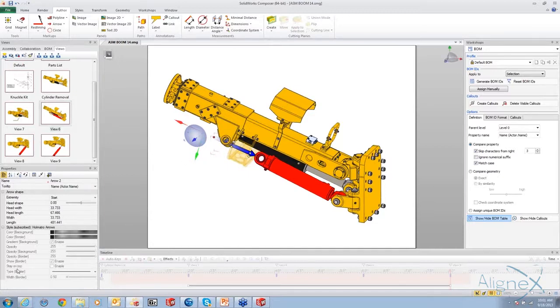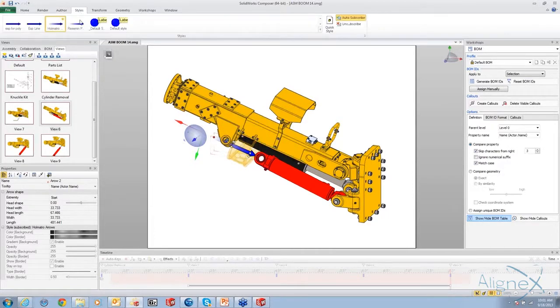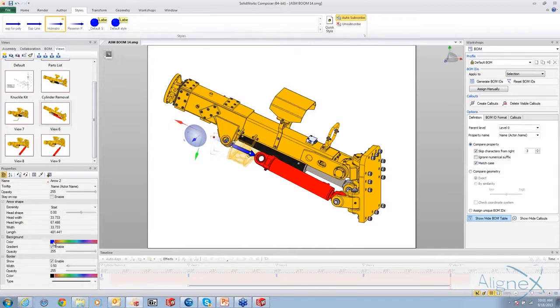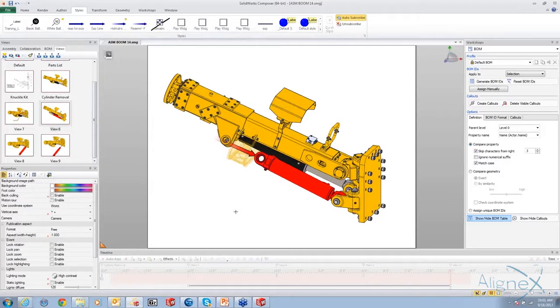All of the properties, you can see right now, I can't change any of the properties because they are specifically chosen to a very specific style. And if I want to make a change maybe to the color of that, I would have to tell that arrow to unsubscribe from that, and then I can come in here and make that adjustment to be a different color. So styles are very extensive and expansive, you can do it for labels and arrows and balloons and callouts and all kinds of stuff. There's really no limitation to how we use those styles.